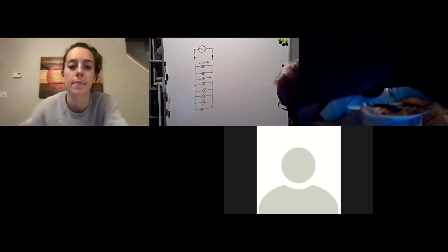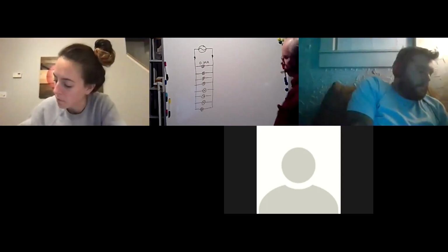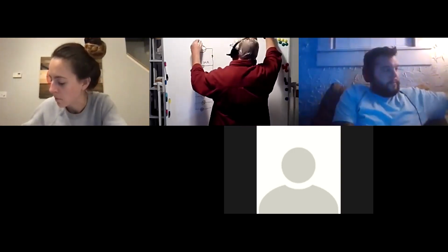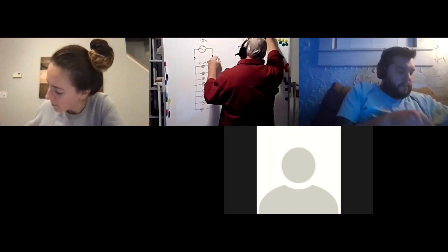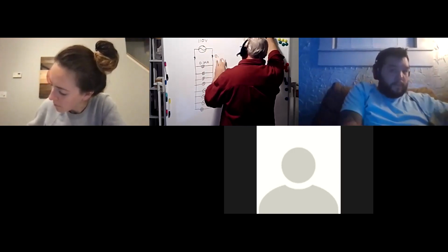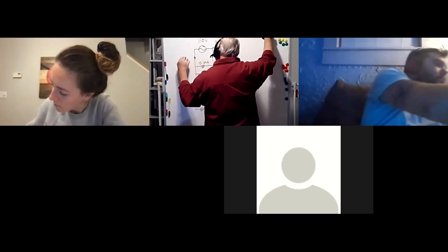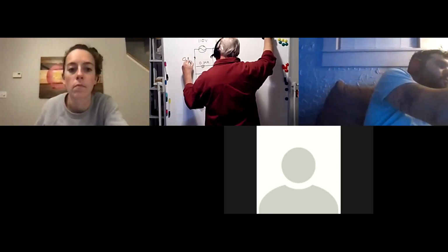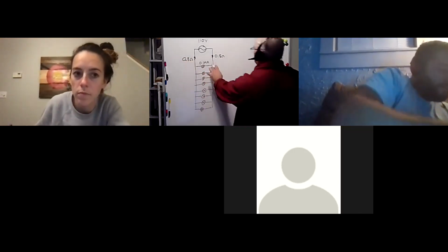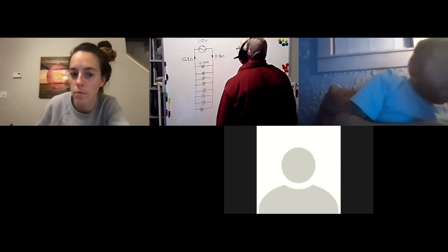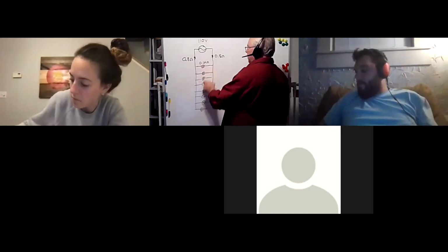And it's 110 volts for the source, and then the two leads have a total resistance of 1.6. So this is an example of a combo circuit. And that means that each one of the leads independently is going to be 0.8 ohms. You didn't have to do this in order to be successful with this problem, but I think visually it makes a little more sense. So the 0.24 is going to be repeated for all of them. And that gives us a sense about what the total current is going to be.